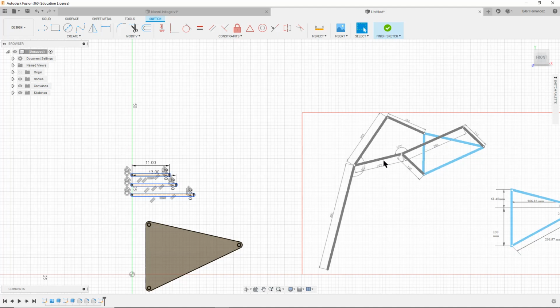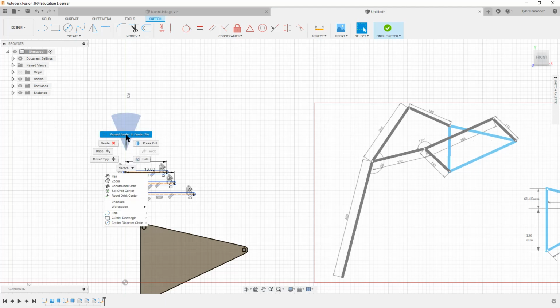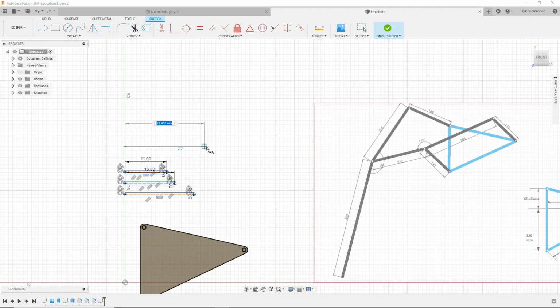And the way I'm going to do that is actually with tools we've already seen. I'm going to make a slot, I'm going to attach another slot to it, and then I'm going to use the sketch dimension tool to make the angle between them 170 degrees. So let's do that. I'm going to right click, repeat, make the first slot, which is 288, you can see here. So I'll do 28.8, click and drag and make it 1 millimeter thick as before and press enter.